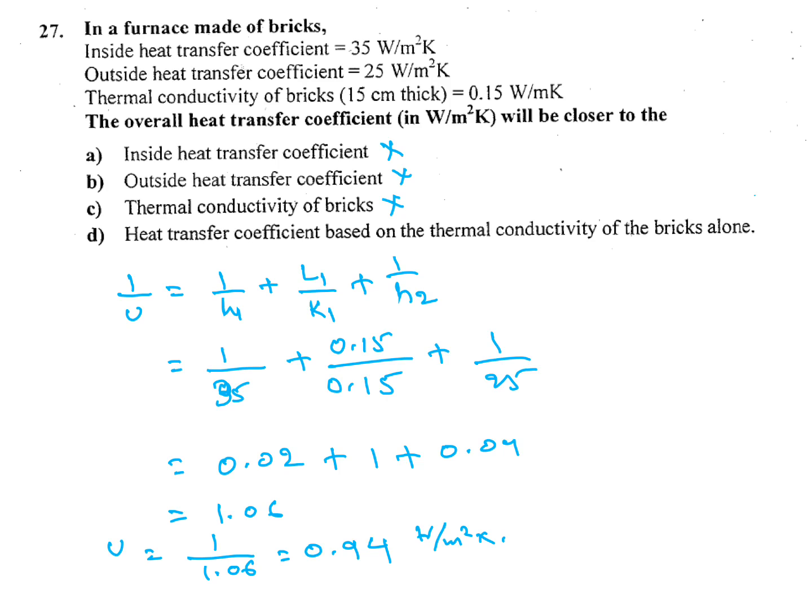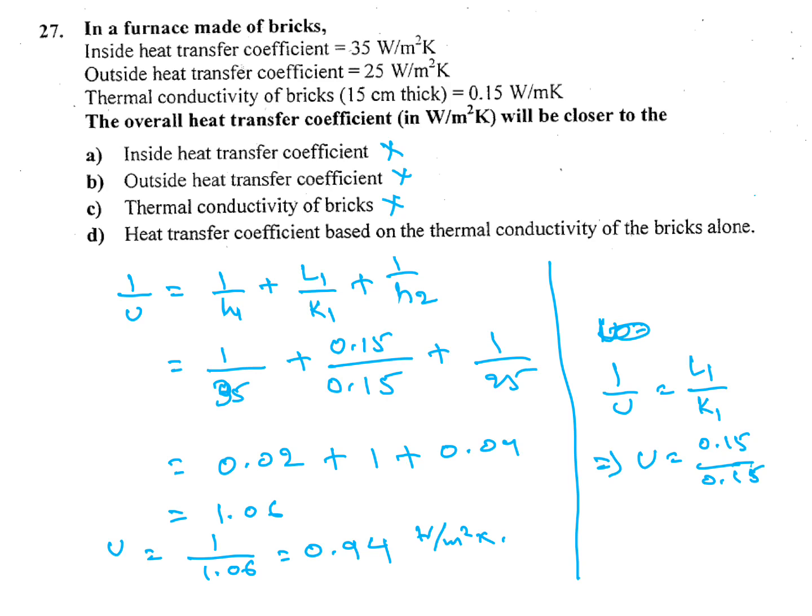We go for D. Heat transfer coefficient based on thermal conductivity of bricks alone: U equal to K1 by L, 0.15 by 0.15, we get 1. 1 is nearby 0.94. So D is our answer.